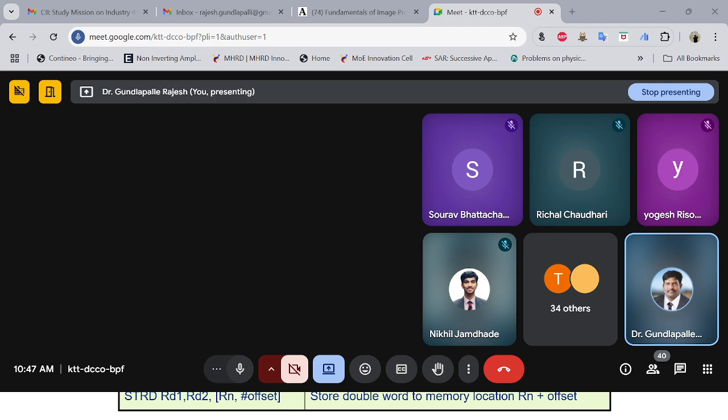So what is meant by loading? Loading means getting the data from the memory. Storing means putting the data into the memory. So, LDR is an instruction, and the suffix refers to what data type we have to move, whether it is 32-bit or 16-bit or any other data type. If you want to move a byte, then it has to be referred to as B. So load byte to the register Rt from Rn, plus if you have any offset, that offset can be added over here.